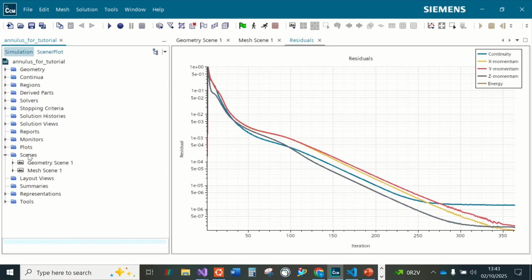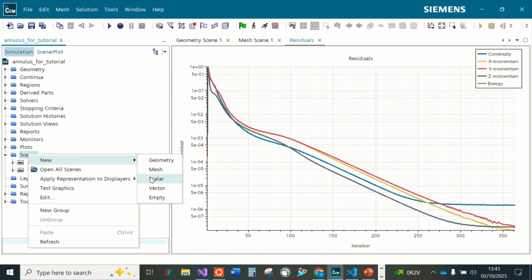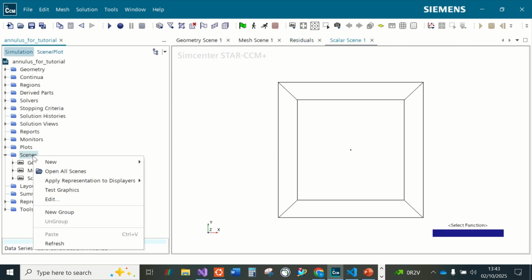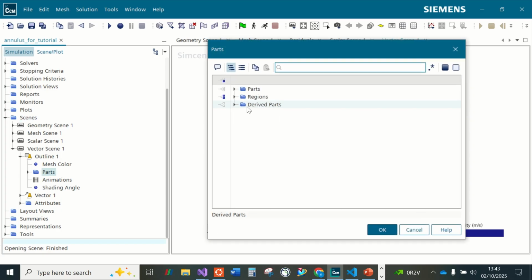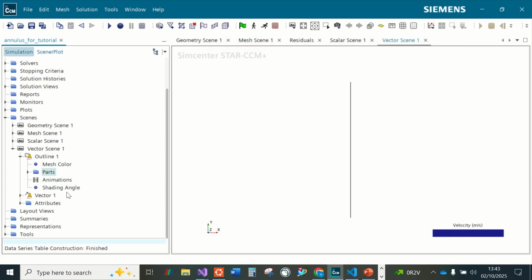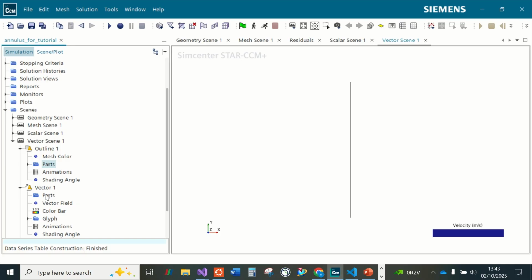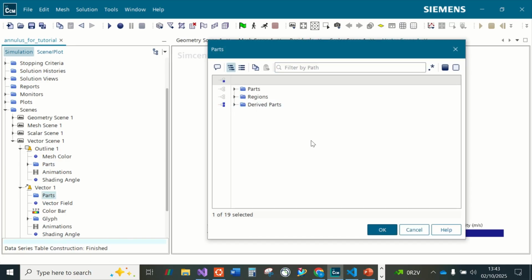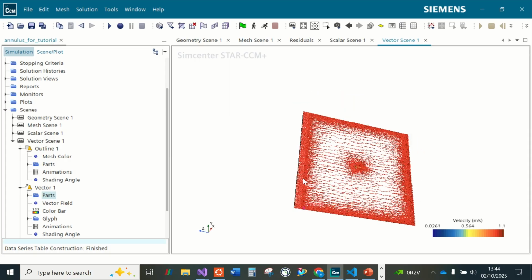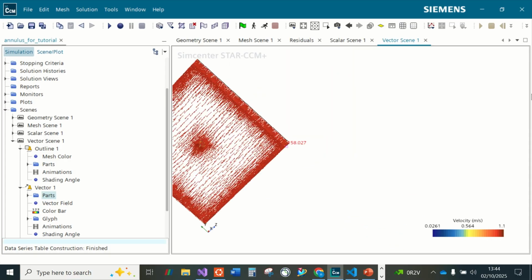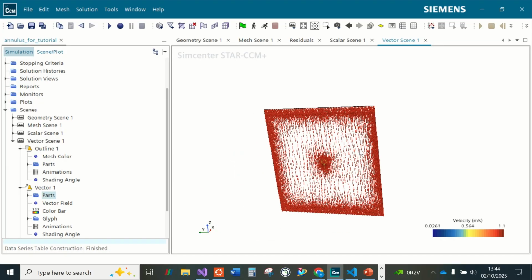This also took a while, so I'm skipping the waiting, but if you're running this for yourself, unfortunately you're going to have to wait. And then here we just want to plot the results. So I'm interested in plotting the pressure and also the velocity vectors, so that's what I'm going to do here. First we're going to plot the velocity vectors in this mid-plane past the bullet.